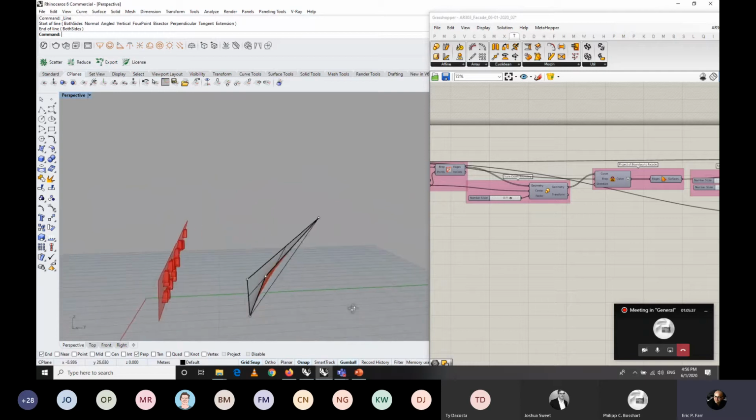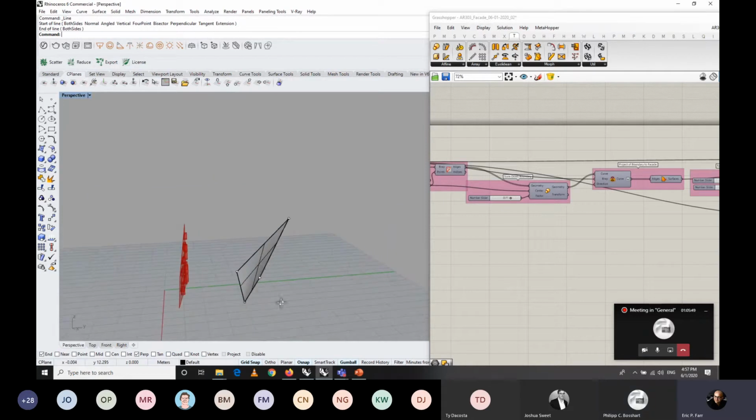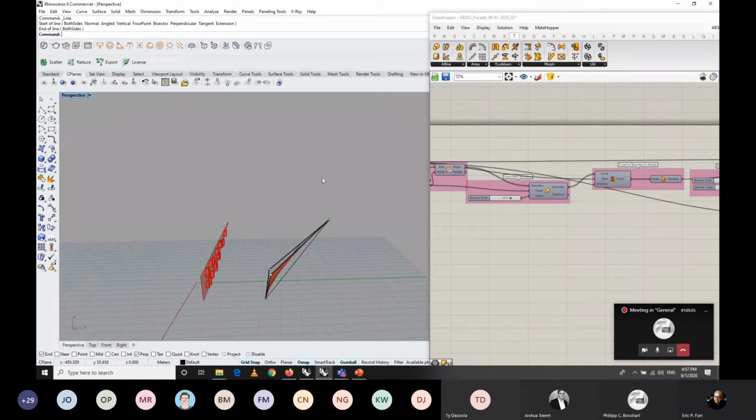Instead of using this surface, we need to have a crinkled surface, 2 surfaces actually, and divide it into 2 triangulated surfaces. That's the only way we do it most of the time if you're having a panelized surface. Rationalizing, yes. There are only 3 points: if you have only 3 points, you can be sure that one surface is going through those 3 points. If you have 4 points, you never know. More than 3 points, you never know.